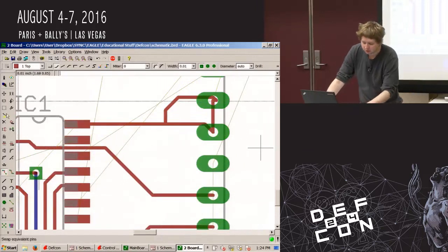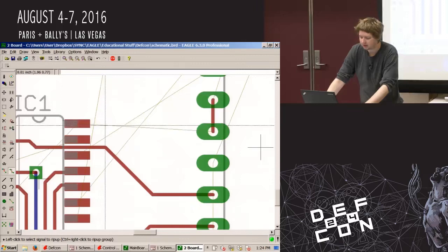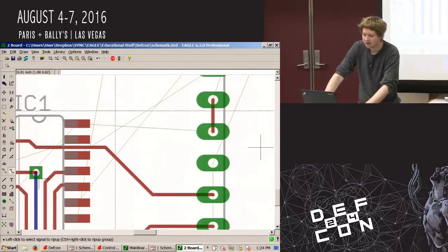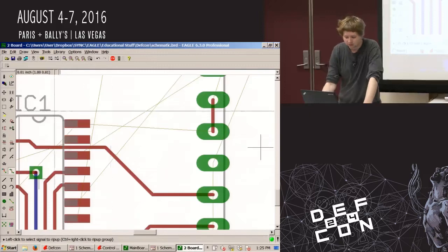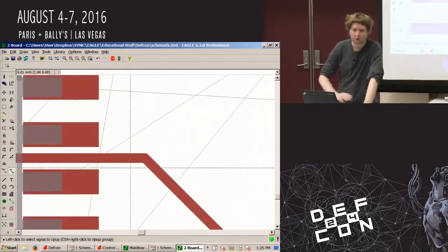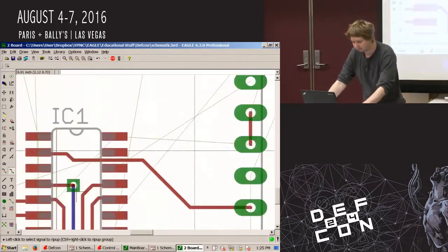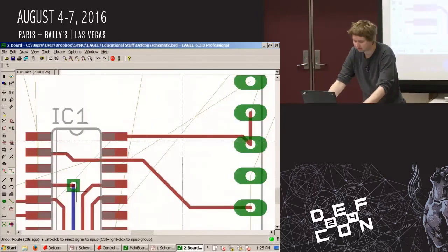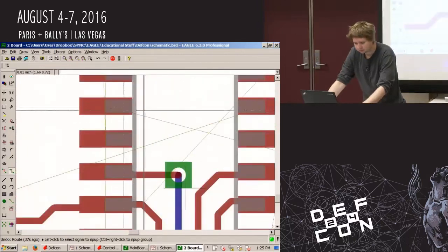Okay, so that's a weird thing, but if I go in and just delete this trace here and I click again, it deletes everything. And if you have a single trace that's running through most of your circuit board, like if you have the plus 5 volt line or something like that, and you're zoomed in way close like this and you don't notice you just wiped out half your board, then it'll ruin your day. So just something to be cognizant of. Crap.